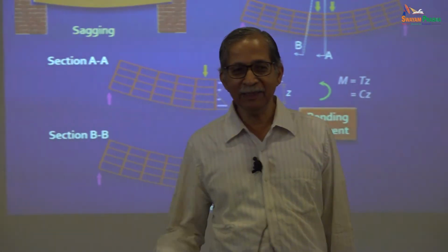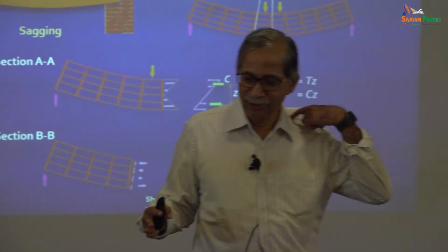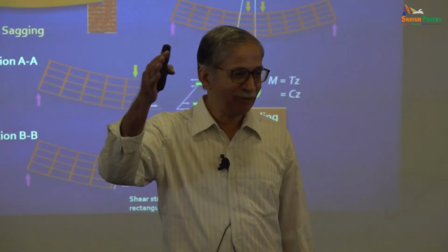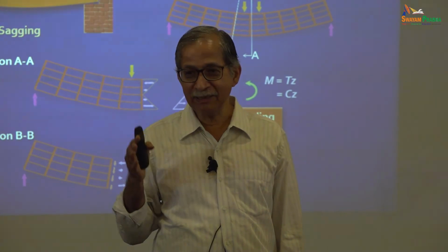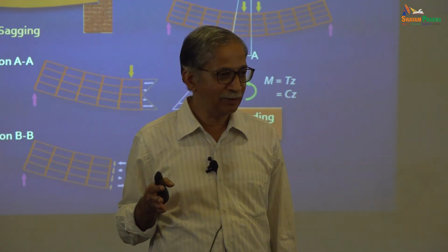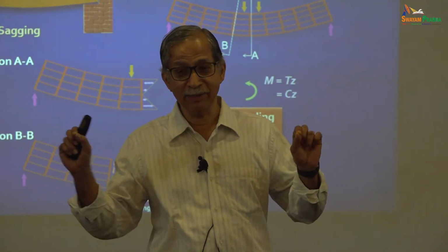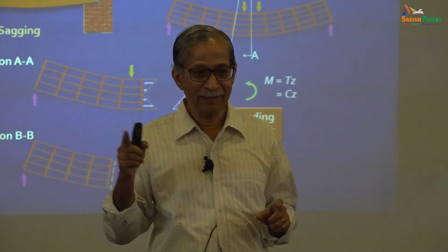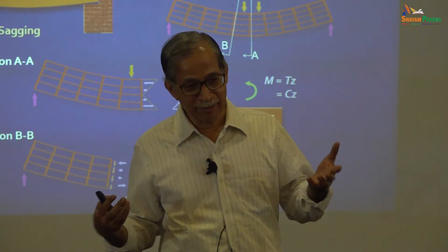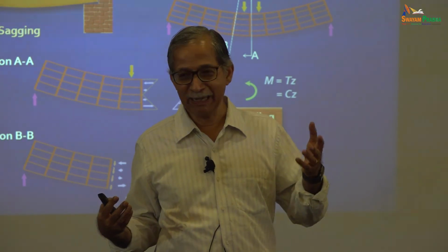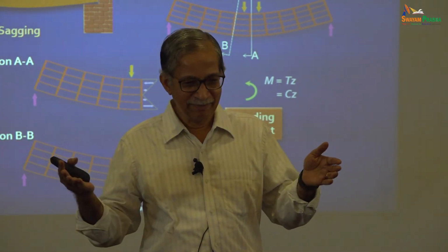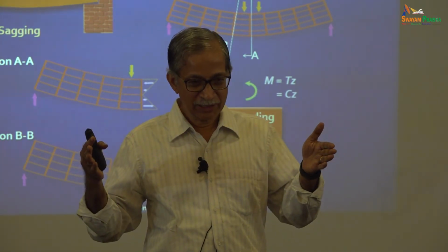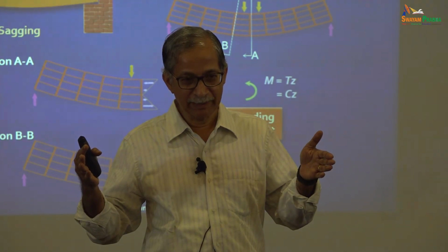So normally we, especially when you do reinforced concrete design, we say V for shear, right? V says it's vertical force, because we are assuming the beam is horizontal. That itself is wrong. Here we'll use S because it need not be a horizontal beam, it can be an inclined beam, but traditionally V for shear, vertical force, right?